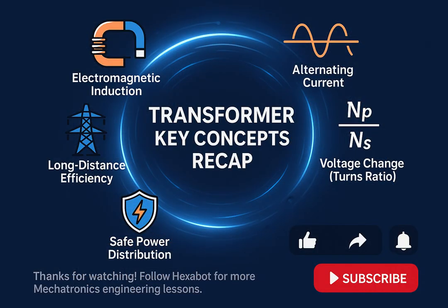To sum up, a transformer transfers energy using electromagnetic induction, only works with AC due to changing magnetic fields, changes voltage level using the turns ratio, reduces power losses in long-distance transmission, plays a key role in safe and efficient power distribution.